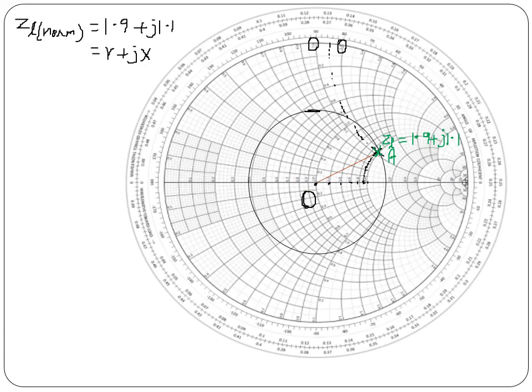Now we have to find out the admittance corresponding to the ZL impedance on the same chart. For that, impedance radius OA is extended to B through the 1.0 center point until it intersects the VSWR circle again.